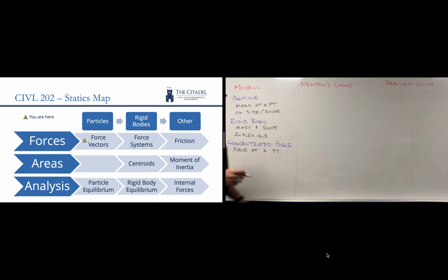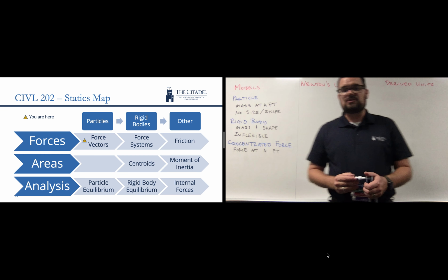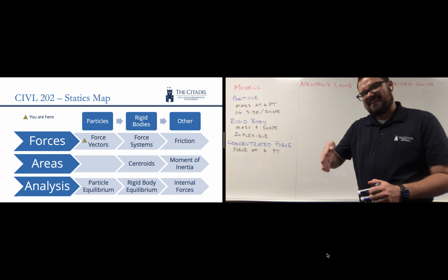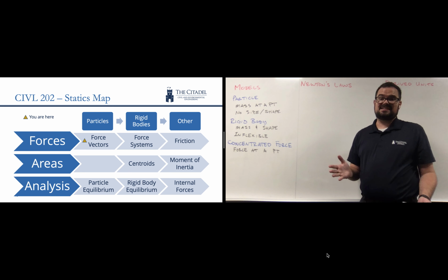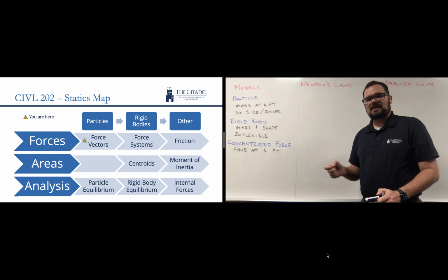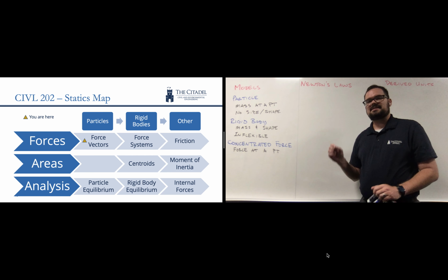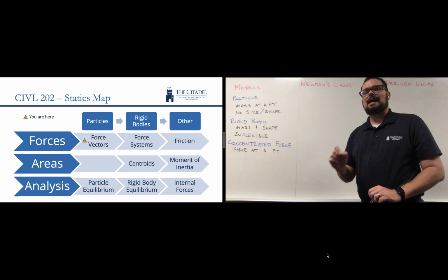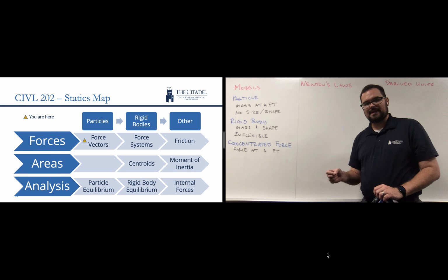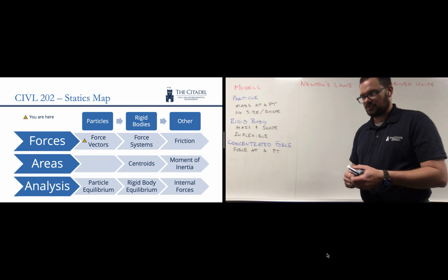Okay, so if we actually applied a force at a point, if we took a knife and we pressed on that knife edge and we focused it down on a point, we would actually cut things. So that's not actually accurate, but sometimes for different problems at an appropriate scale, we can model it as a force, a push or pull, applied as a mathematical point, and that's just fine. So that's a concentrated force.